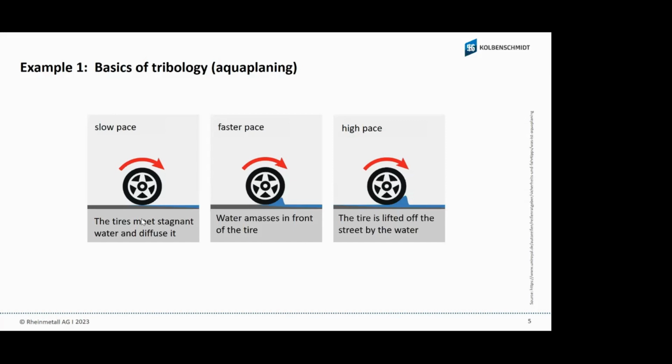We have contact between the piston ring and the surface, and this is also why, at top dead center, in the area where the piston ring moves up and down at the top position, we have much more wear than on the bottom side. We have much higher pressure at the top, and we don't have the speed, so the piston ring jumps between the oil and has contact with the surface of the liner.